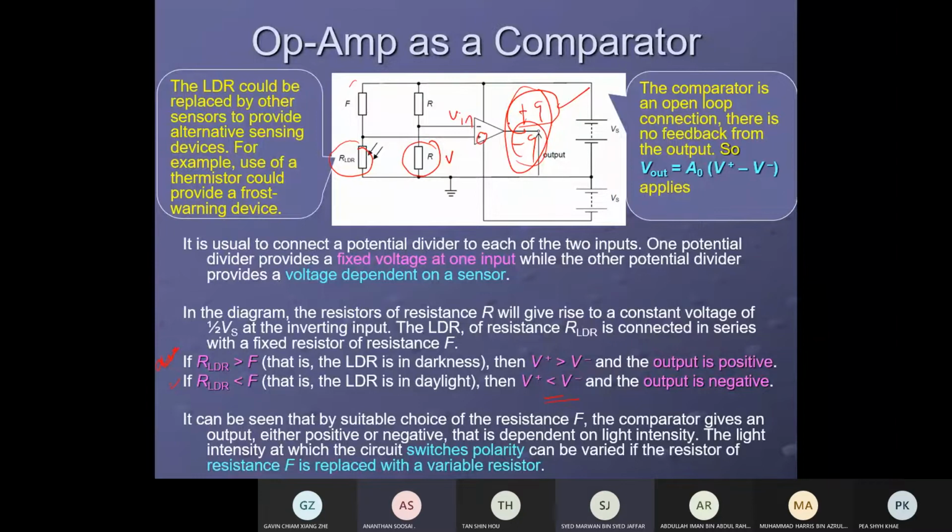If it never saturated, if it was like a positive 3, some intermediate value, it would be difficult to switch the alarm on or off. Because the op amp acts as what? As a comparator, acts as a switch. Switch means either on or off. That means either positively or negatively saturated. So it's good to be saturated, right? It's good to be saturated in a switching system.